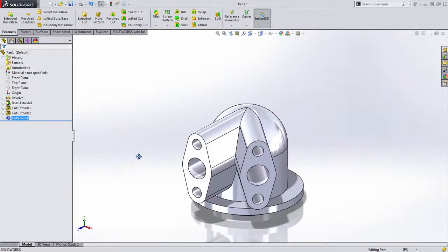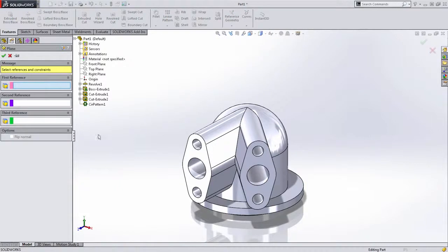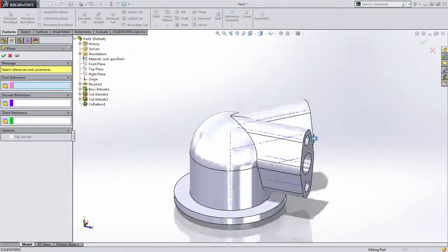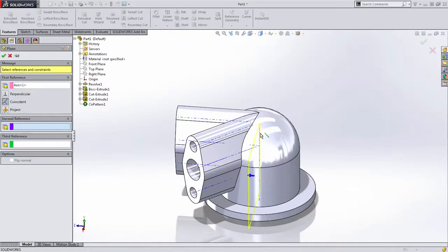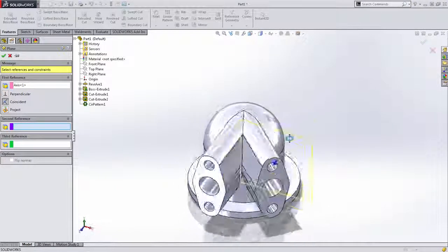I'm going to do it using some construction geometry. I'm going to start by creating a reference plane. Now, a reference plane can be created by selecting a variety of pieces of geometry. I want to find the center of my part. SOLIDWORKS actually provides you with something called temporary axes on every cylindrical part and feature you create. I'm going to choose the center line of our whole part file here. That's all I need it for, so I'm going to just toggle those back off for clarity.